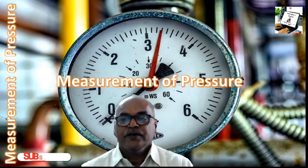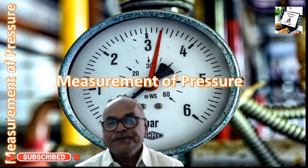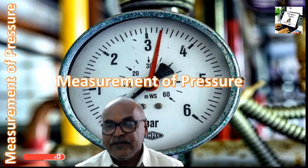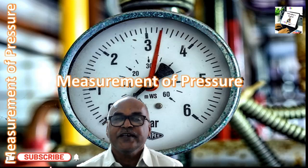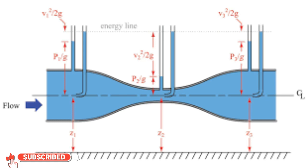So friends, today we have studied the measurement of pressure devices: manometers, simple manometers, and differential manometers. In simple manometers we studied the piezometer, simple U-tube manometer and micromanometer. In differential manometers we studied the two piezometers, that is, two piezometers connected to two pressure points, and let us say H1 and H2 are the different elevations. So H1 minus H2 will give the difference between the two pressure points. PA by W minus PB by W is equal to H1 minus H2.